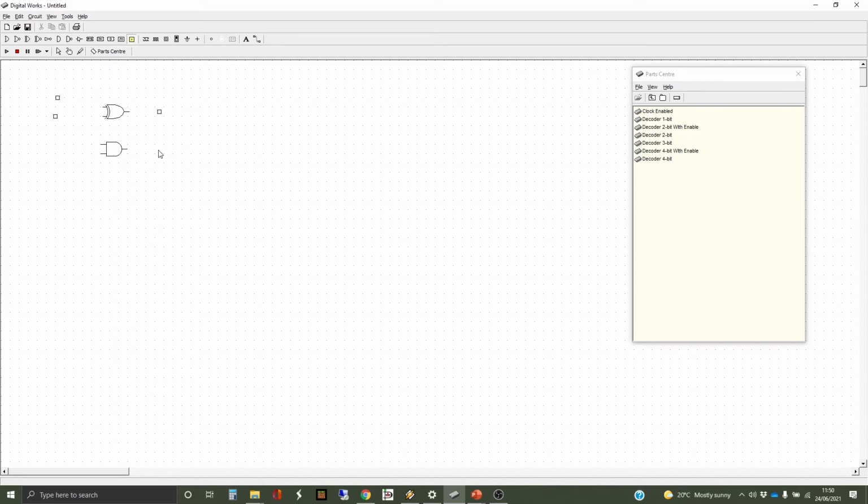Here we go. And we're just going to wire these up. So the two inputs go to both inputs for the XOR gate and in parallel to the AND gate there, and connect those tags to the output. And we're going to then open the template editor so that we can turn this into a macro.